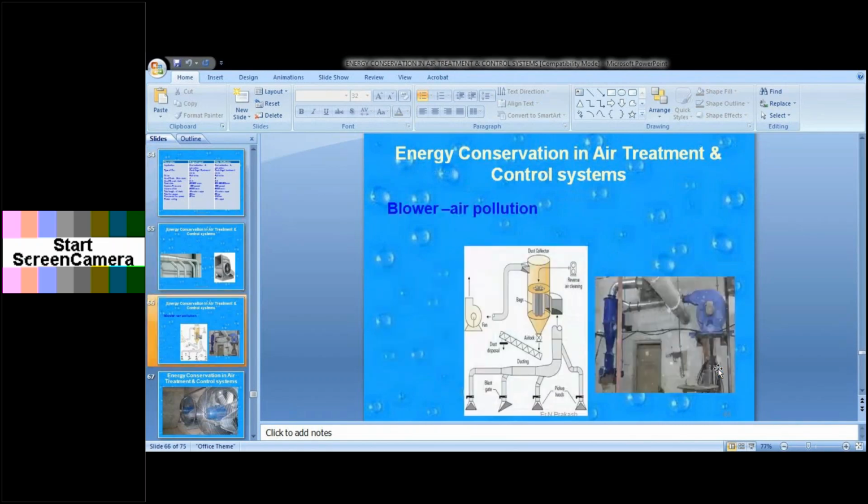So we have done this even in an automobile factory, in one of the TVS groups. We have done it in Brakes India. I remember Brakes, the place where they had given for air pollution control. Earlier, the capture velocity was more. They had given a very big fan, and you know that in the process of machining, there will be acid and fumes. So to capture the fumes and take it to the scrubber, they installed a ducting system and fans.